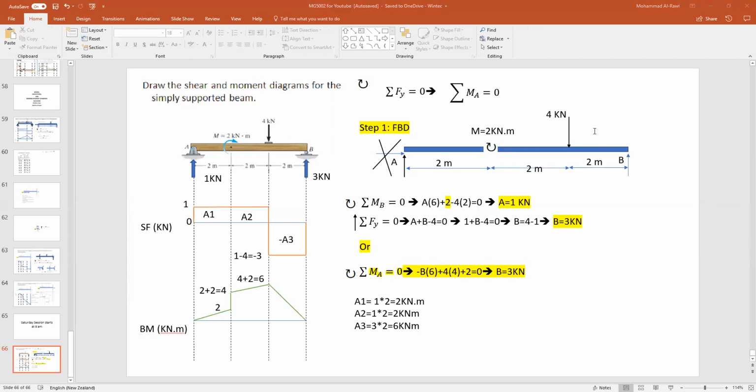So why is the bending moment diagram a straight line going up? Again, because it's clockwise. So because it's clockwise, we'll go up. And that's the good thing about it. Since it's clockwise, I assume it's going up. If it was counterclockwise, we'll go down.